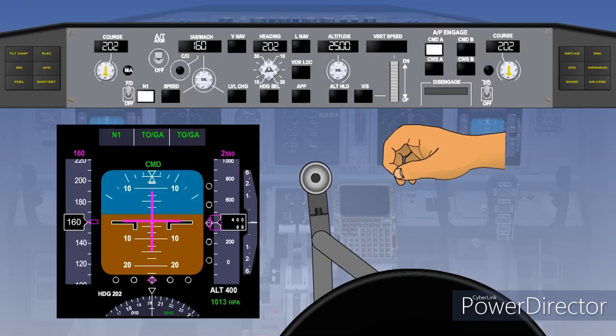Go-around thrust is not necessarily full thrust. On some aircraft types, pressing the Takeoff Go-Around switch a second time will advance the throttles to full thrust. The pitch channel of the autopilot pitches the aircraft up to achieve the pre-programmed vertical speed. The roll channel of the autopilot maintains the track that existed at the time the Takeoff Go-Around switches were pressed. The objective is to fly the aircraft up directly over the runway centerline. Go-around is a one-button operation to keep the aircraft away from any danger.